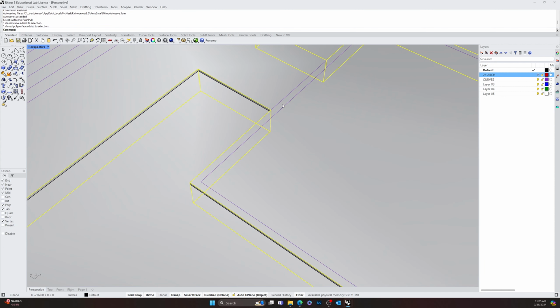And then I'm going to draw a line from this point here to that point here. And I'm going to array, enter, this object, enter. Let's do array, curve. Select object to array, and enter. Select curve path. Okay. And then the number of them, 20. Enter. And perfect.